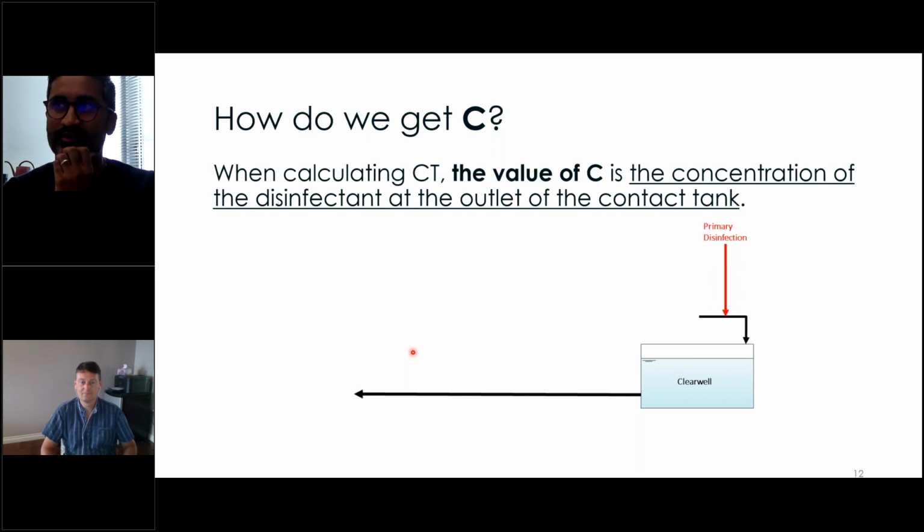What a tracer allows you to do is basically look at how much time a particular liquid is spending in your tank and the distribution of that. Then you can make your RTD curve from that, based on collecting the dye at the outlet and seeing how long it takes for all that dye to come out. And then based on that, you can figure out where that 10% T10 is located.